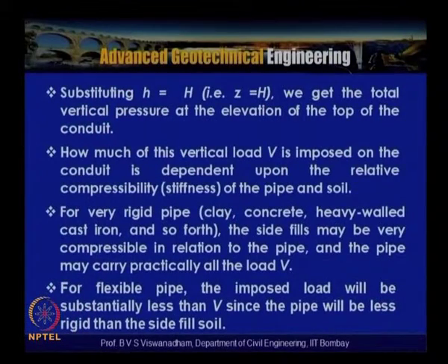In case of flexible pipes, the imposed load will be substantially less than V, since the pipe will be less rigid than the side fill soil. So how much vertical load is transferred onto the conduit depends upon the relative compressibility or relative stiffness of the pipe and soil, that is the pipe soil relative stiffness.